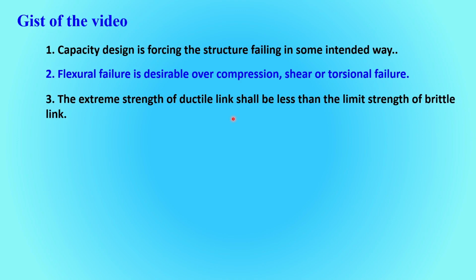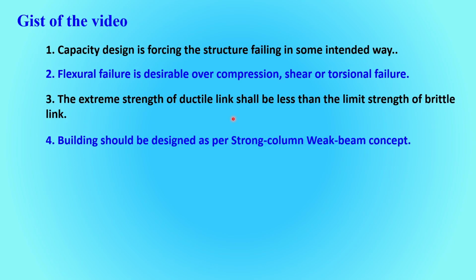The extreme strength of the ductile link shall be less than the limit strength of the brittle link so that the failure of the ductile link is ensured. Buildings should be designed as per the strong column weak beam concept so that the columns are not failing and the beams are failing and able to dissipate energy during an earthquake. Failure of columns may lead to instability, as we have discussed: instability in the physical building and instability in the model in the computer when you are making nonlinear analysis.